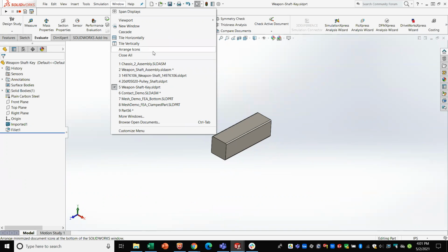This is why when you buy gears or sprockets, the sprocket is a thin disc, but it's got this gigantic thick boss at the hub, and that's because you need that width for the key to be sufficiently big to resist torque.